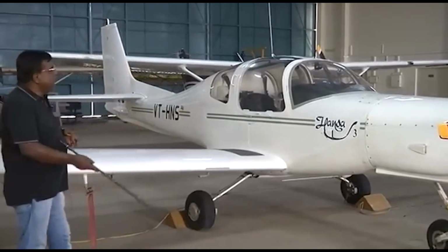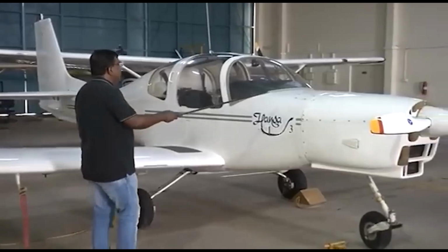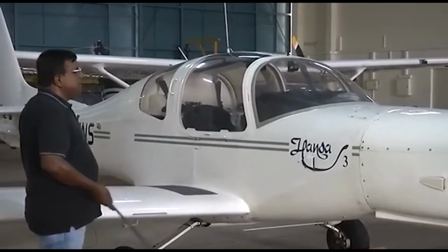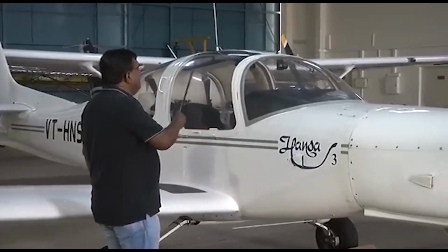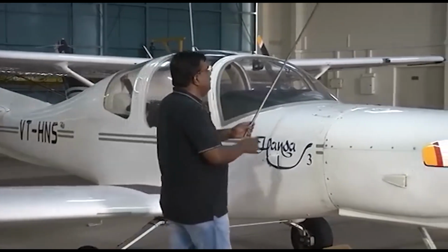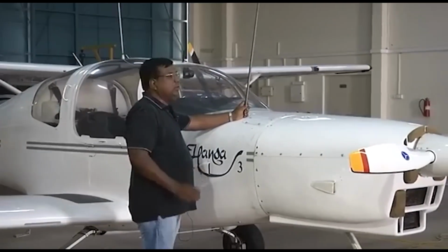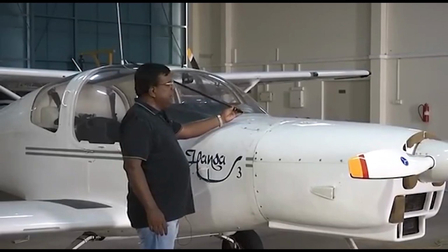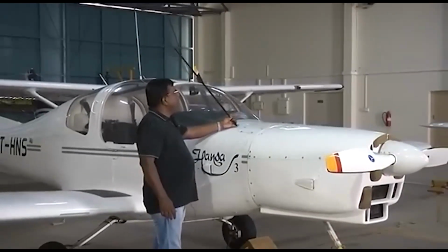So what are the forces? Now let us also have a closer look. If I separate out the fuselage, wing, tail, and other components, I can fairly do an approximation. Let us say the force on the fuselage is acting somewhere here. Okay? That's the lift. I'm talking about the lift part. Similarly, drag will be acting like this, depending upon the velocity direction. Do not forget, lift will be perpendicular to the velocity, and drag will be opposing the velocity.